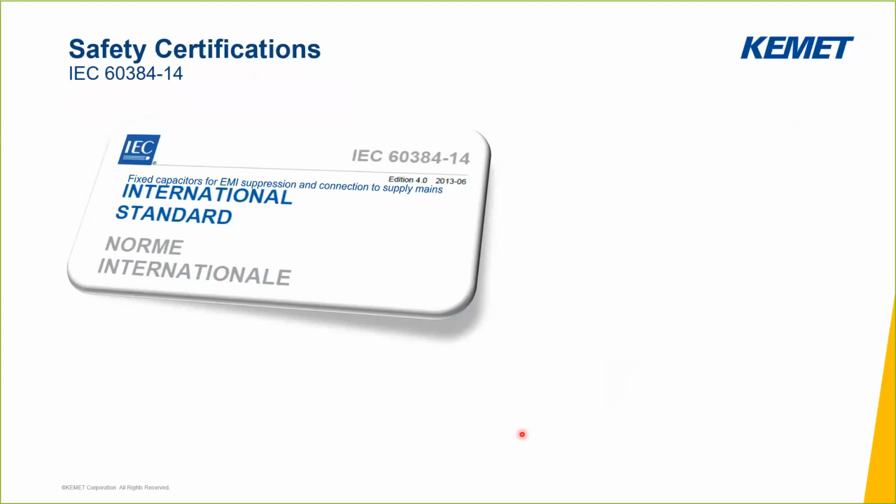Now, to ensure safety capacitors are reliable for the line-to-line and line-to-ground applications, they must be certified to internationally accepted standards. The main standard for safety capacitors is the IEC 60384-14, which is titled Fixed Capacitors for EMI Suppression and Connection to Supply Mains. This is an internationally recognized standard and is referenced by all suppliers who produce safety capacitors. UL also adopted this standard to create the UL version, but it's pretty much identical to the IEC version. There are only a few minor deviations.